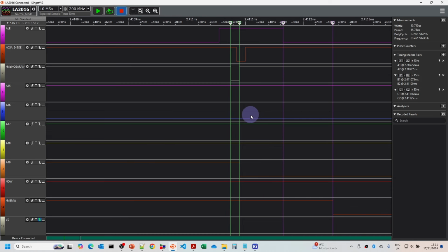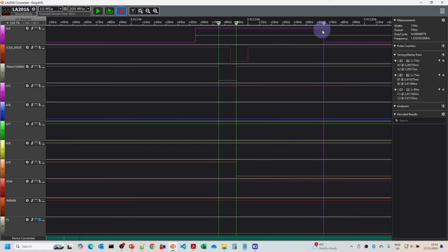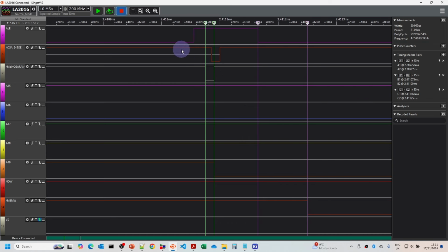So in fact, our chip enable can include a condition on the address latch enable, and we'll only allow chip enable to be active if address latch enable is low. So we're going to need to add the address latch enable into the decoder PLD, and update the rule to include this for the CGA RAM. So we just need to update the KiCad diagram, update the rules for the PLD, and wire in the extra address latch enable, and hopefully this should get rid of our stray characters and our snow when we're not updating the video card.